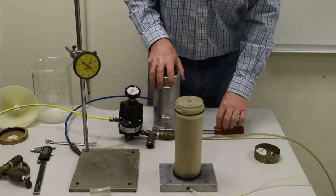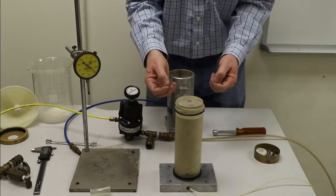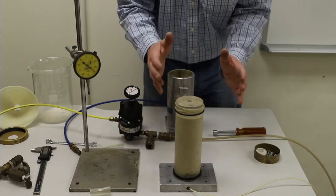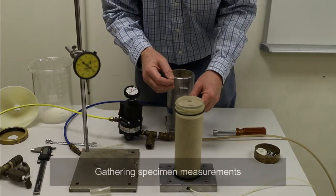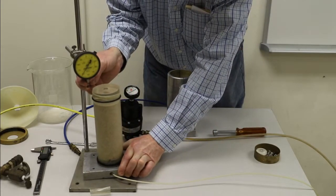11 inches of mercury is about a third of an atmosphere, maybe 30 kPa. So this is not a particularly delicate specimen. It's a dry sand. It's under significant effective stress, so we don't have to worry about being too delicate with it now. What we will do is put it back under the top cap.